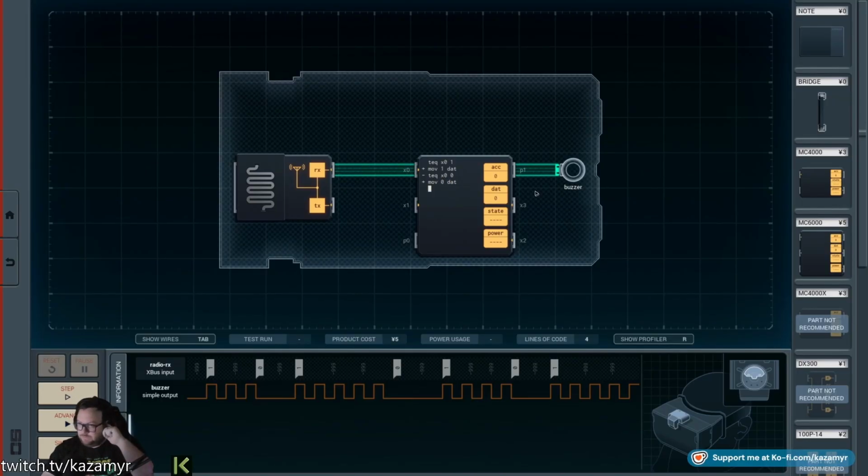And the reason why we need DAT is so we can test equal DAT to 1. If our DAT is 1, we're going to move 100 to the accumulator because we start on, right? So we're going to move the accumulator to P1. We're going to not it.